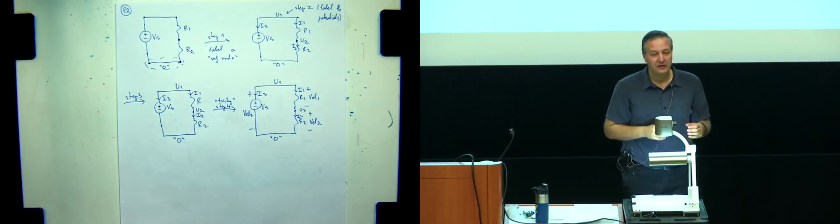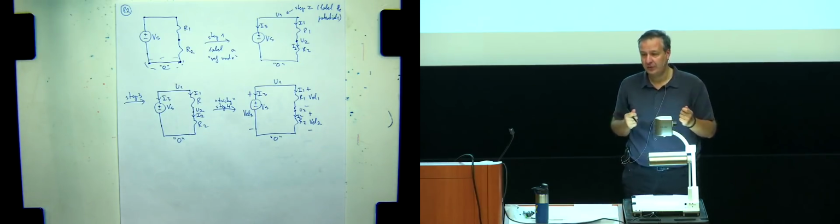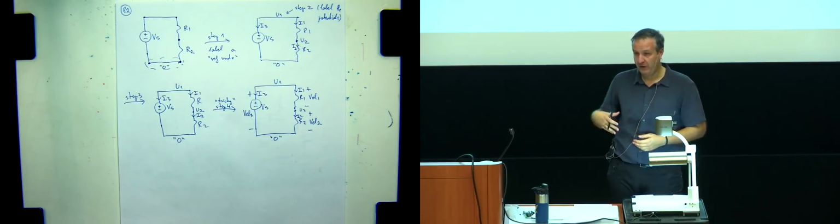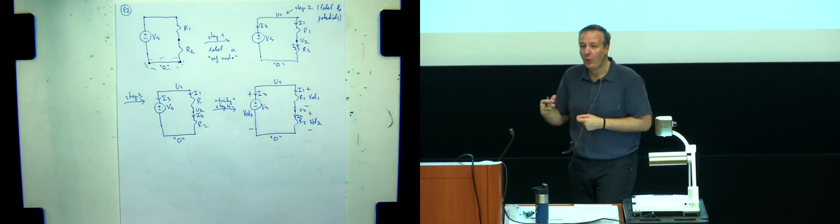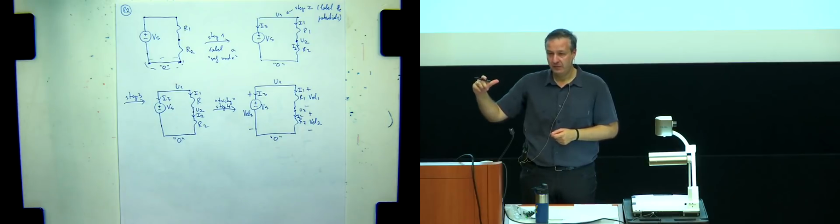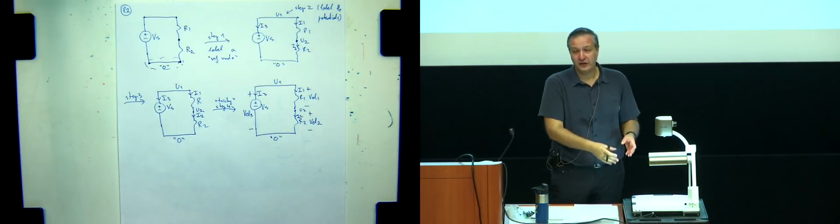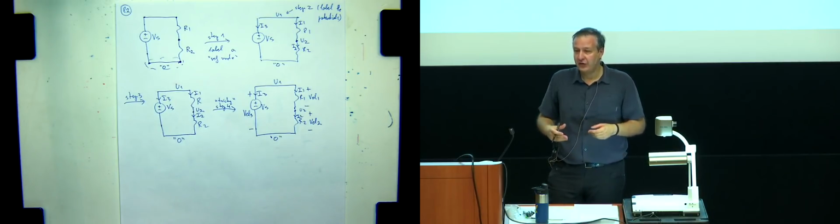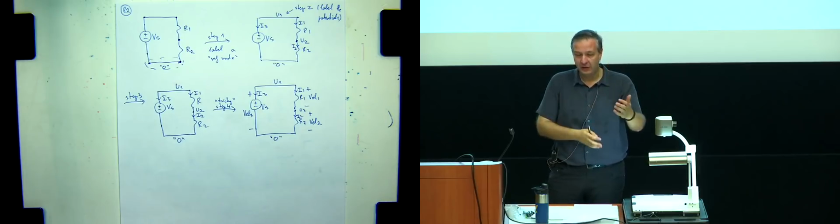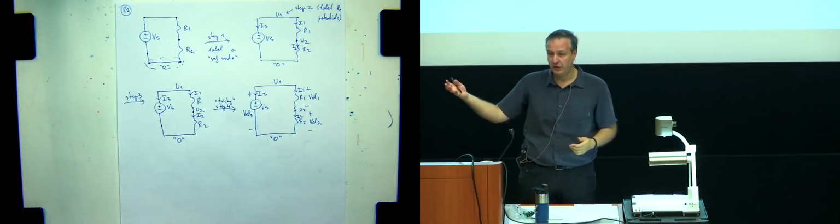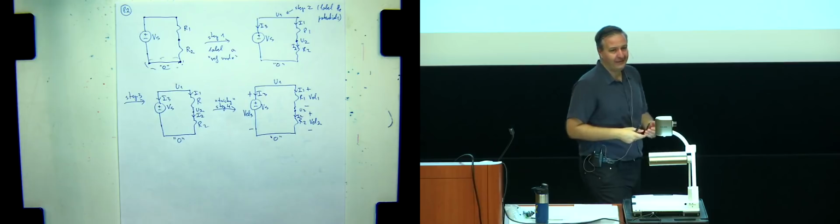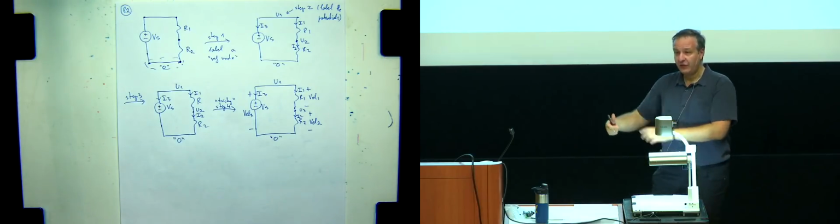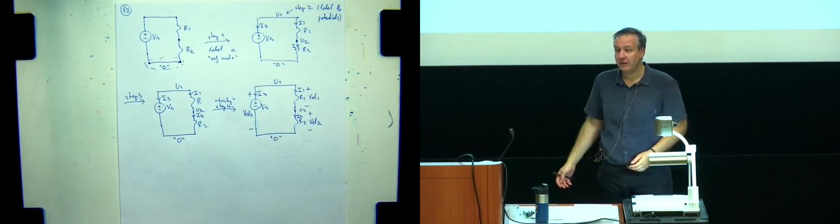When we defined the current-voltage relationships for each element, remember last lecture, we always used that same convention. So that's why you have to do it here as well. Otherwise you would lose the connection between the current through the element and the voltage on the element, and you'd get the sign wrong and everything comes out wrong.